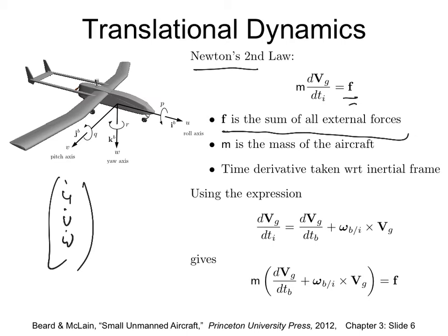I don't know if you remember, last class we ended with differentiating a vector in a rotating frame. The body frame was rotating with P, Q, R. So looked at from the inertial frame, the derivative comprised two parts. That's what we are doing: differentiating a vector. Vg is a vector, right? What is Vg? It's the ground velocity in the body frame, which is u, v, w, nothing else. We are differentiating it in a rotating frame because the body frame is rotating with P, Q, and R. So it has two components: the linear acceleration component and the acceleration because of the rotation. That's how that differentiation works out from the previous class.